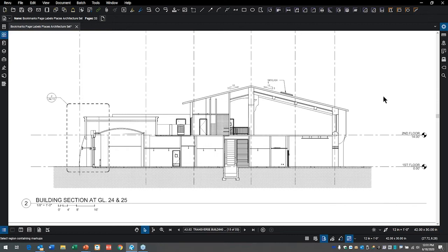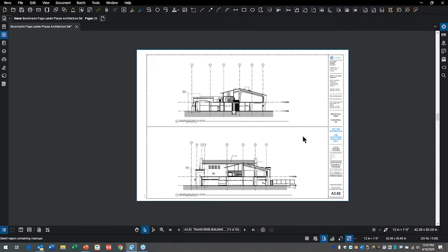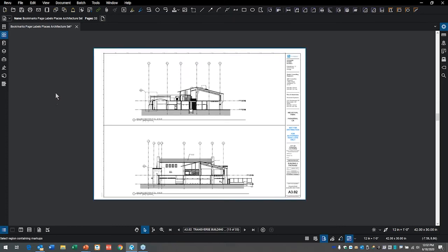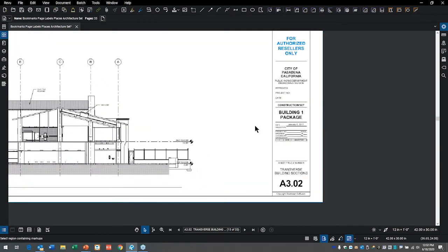Now, I can imagine that that would be a fairly tedious process, right? To go through this entire set of drawings and do that. So instead, what I'm going to show you is how to automate that process. What it will do is I'm going to tell it to look for something. And what I want to look for is, let's say, the sheet number. Anywhere you find that sheet number, create a hyperlink between that bit of data and the sheet number. Okay, so let us take a look at how we can process these things more efficiently.